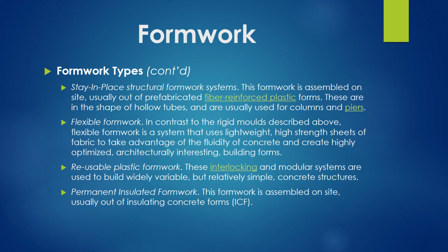We also have reusable plastic formwork. These interlocking and modular systems are used to build widely variable but relatively simple concrete structures. And the last one we have is the permanent insulated formwork. This formwork is assembled on-site, usually out of insulating concrete forms, also known as ICF.